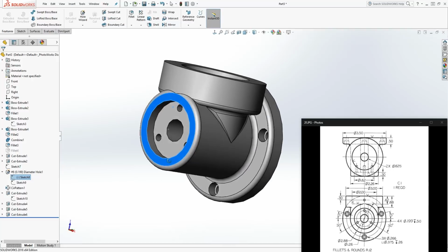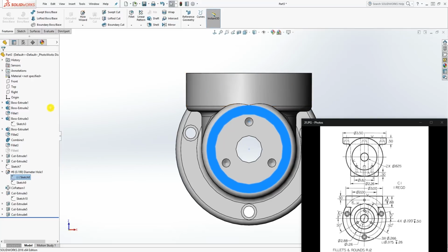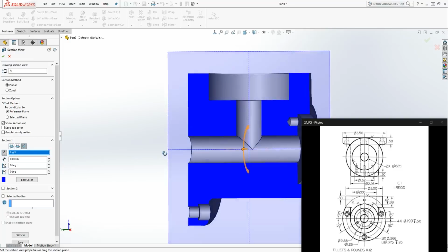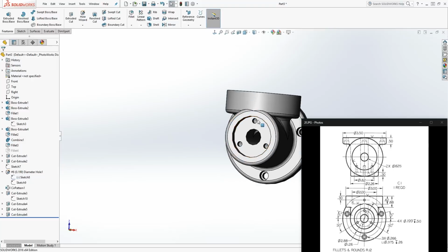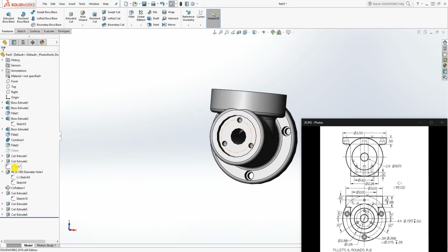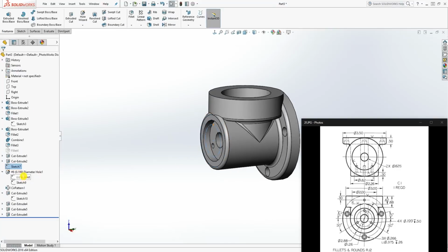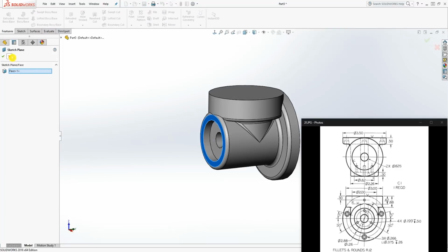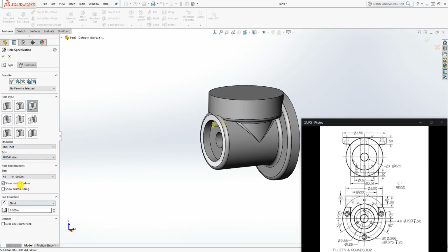So it's still 0.5 in, but now, if I section it, where's my section to? Yes, I believe it's right now. So what I did is just the way we made it. Just go back to this sketch, right click, change the plane and change it to this, and on your hole wizard right click, pull the drop down, this sketch, change the plane and change it to that face, and it should move everything for you. If I go in here, everything is still the same, so it's still 0.5, 0.199.